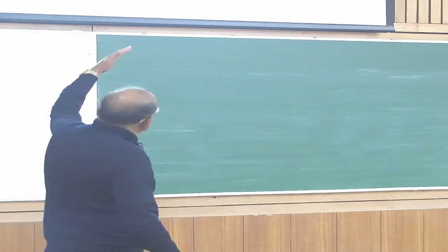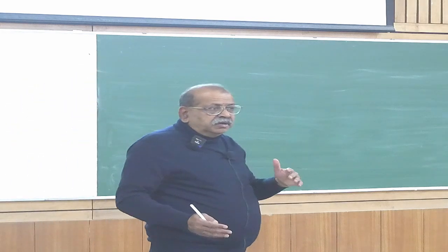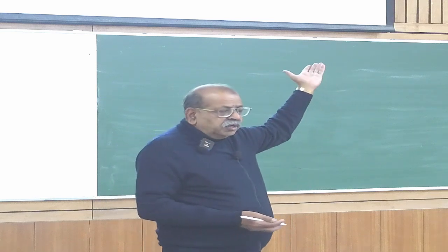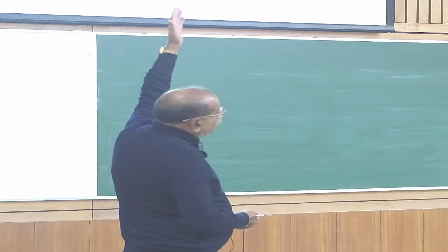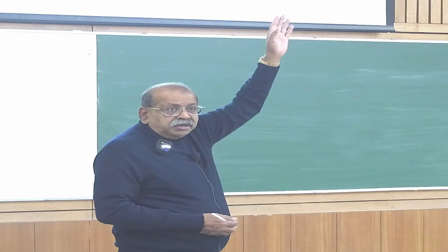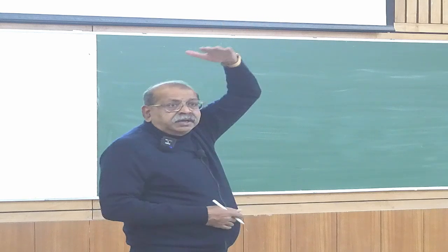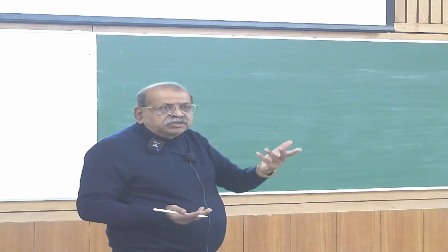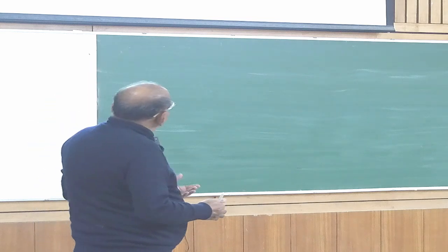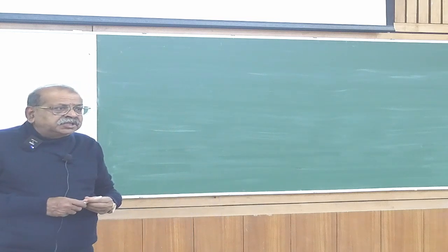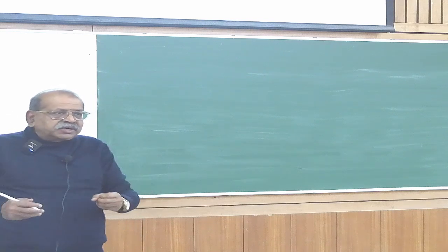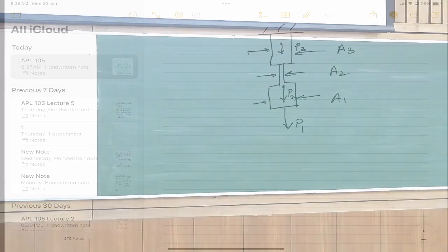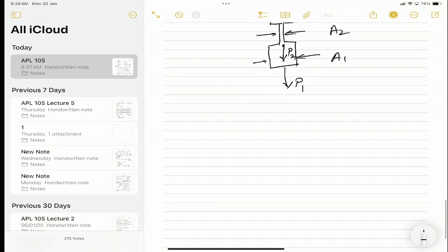The advantage is that if you cut from the bottom, you will be able to find all the forces, because if you cut from the top, you will first have to find the force and the moment at the reaction supports. Then you will find delta at each stage. So, the eventual extension will be the sum of all the forces by AE.